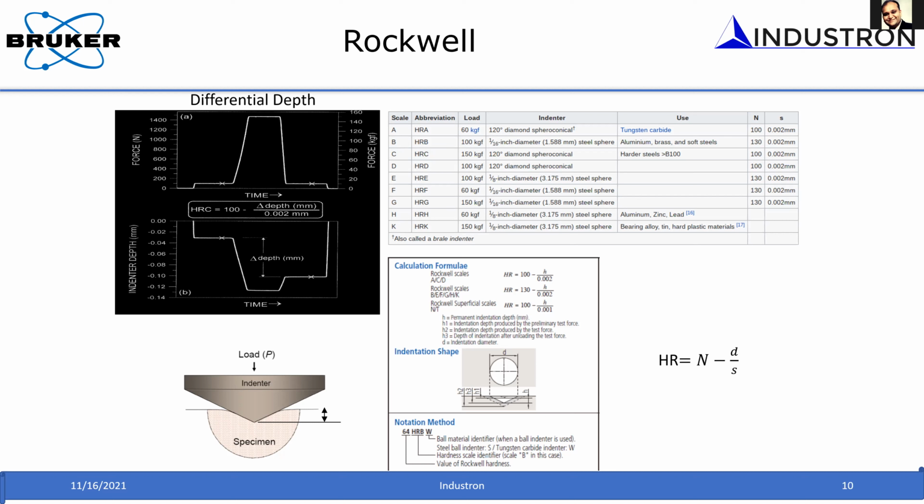So in most of what I've been talking about in hardness testing, you just apply a load with a probe of known geometry and measure the depth of penetration or the size of the contact, the size of the impression that it makes. It is as simple as that. You need to apply a load with a probe onto a sample, and you should know the load that you apply and measure the size of the contact, either by an optical microscope or the penetration depth of the indenter into the material.